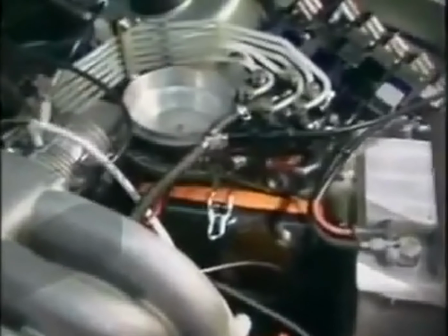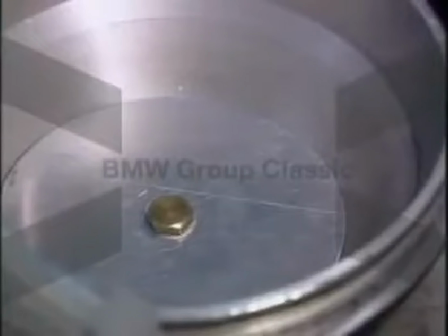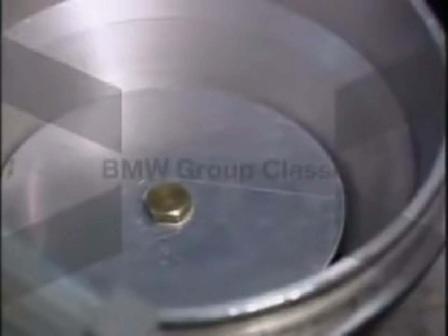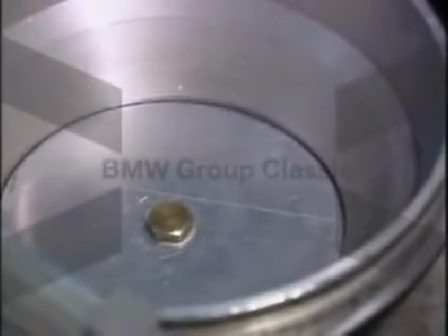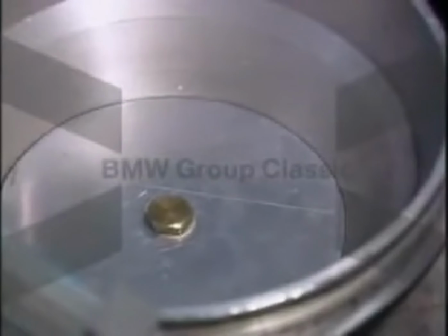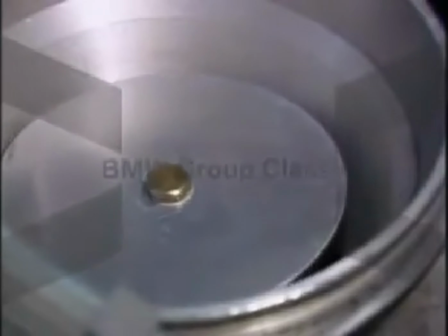now to inspect the mixture control unit. In order to check that the sensor plate is correctly positioned, we've removed the air intake dome at the airflow sensor. Correctly positioned, the upper edge of the sensor plate is flush with the base of the air funnel. It must not be seated higher than the funnel base or maximum 0.5 millimeters below. The zero position can, if required, be adjusted by bending this leaf spring.